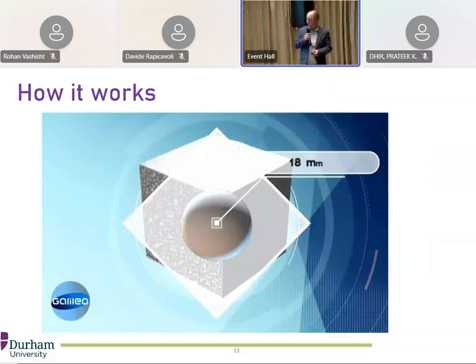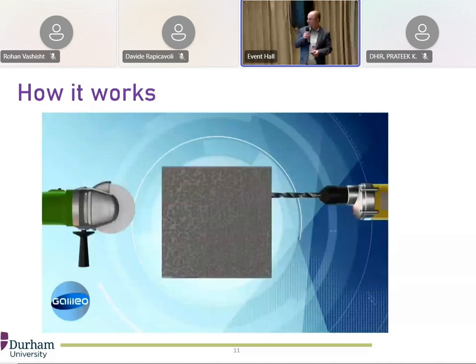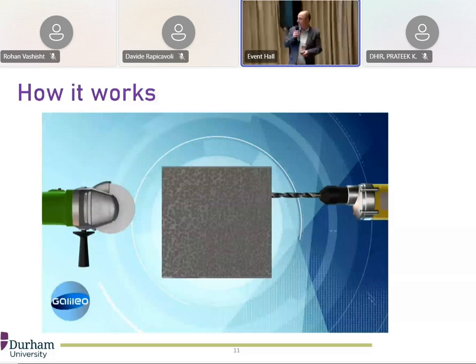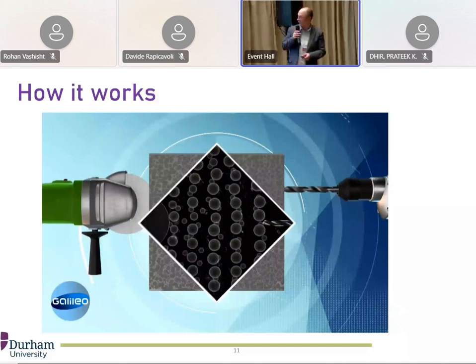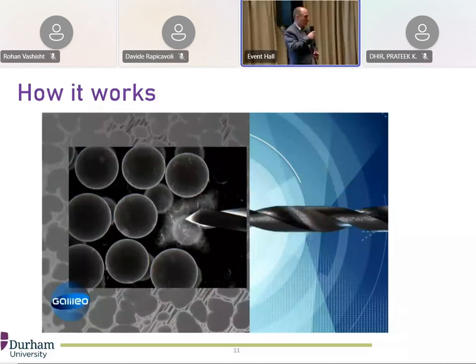So this is the principle. The principle is that we basically leverage vibrations. When you try to cut it, there is an internal resonance between the spheres and the cutting blade, and this creates very high strain rate loads at the interface, and these vibrational loads destroy the blade.